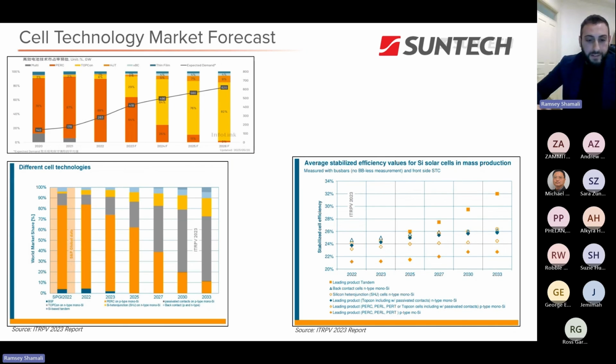But for TOPCon, there is still headroom to increase the cell efficiency as everyone's manufacturing process is optimized. To make TOPCon, there are actually 3 or 4 different ways. Throughout these methods, one or the other could be improving over the next few years, and that could drive the efficiency higher and higher, to reach that max theoretical limit of around 28% cell efficiency for TOPCon. So basically, there is growth available for TOPCon, and that's also why I think the price will drop. I hope that answers your question.